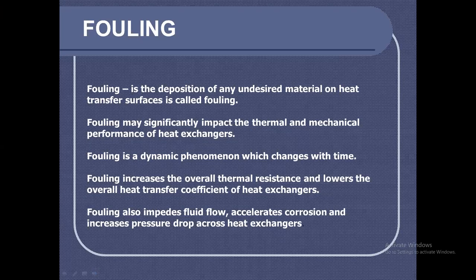Now, fouling, we know fouling is the deposition of any undesired material on our heat transfer surfaces. This may significantly impact the thermal and mechanical performance of our heat exchangers. It's a dynamic phenomenon, meaning it's ever changing over time. It increases the overall thermal resistance, and thus it lowers the overall heat transfer coefficient of your heat exchanger.